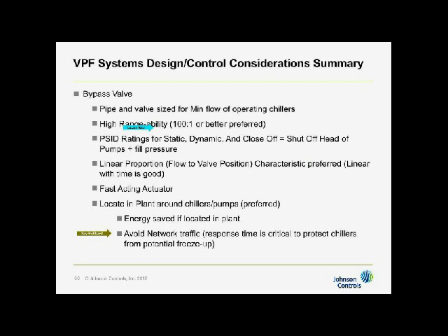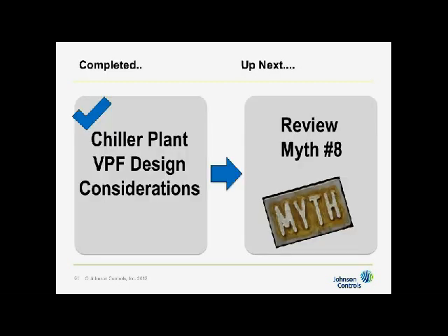Because if I put it all the way out at the end of the system, the bypass flow in bypass mode has to travel through the entire system all the way to the end and come back. And that's just wasting pump energy during bypass operation. So locating it in the plant saves energy, and it also makes it easy. So that's the design considerations for VPF on the chill water side.